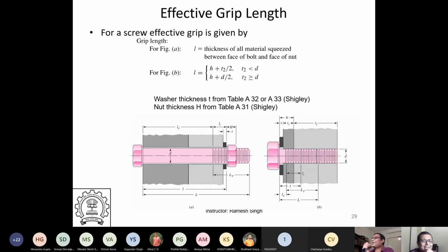Yes, to see how it deflects under the load is fine. Typically, with these structures, we need to know the stiffness because their structural dynamics also responds to that. You need to know because there are additional compliances and you need a stiffer member. The moment you're bolting, your bolting will have lower stiffness. Of course, it will deflect under the load. That we need to know because these are joints, and the stiffness is lower than if it were welded or permanently joined or fully bonded.